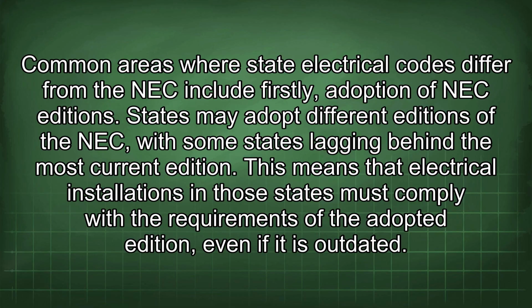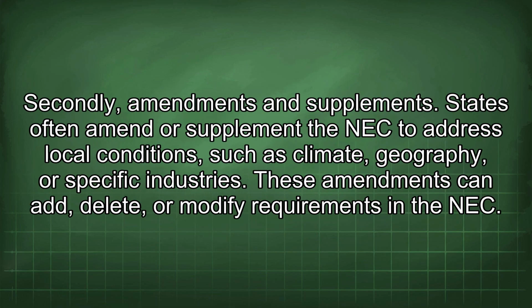States may adopt different editions of the NEC, with some states lagging behind the most current edition. This means that electrical installations in those states must comply with the requirements of the adopted edition, even if it is outdated. Secondly, amendments and supplements. States often amend or supplement the NEC to address local conditions, such as climate, geography, or specific industries. These amendments can add, delete, or modify requirements in the NEC.